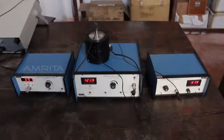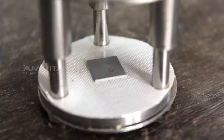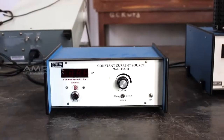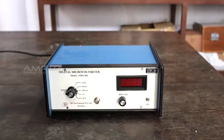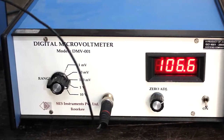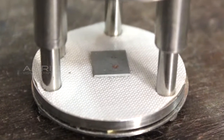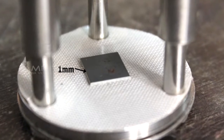Apparatus: the experimental setup consists of probe arrangement, sample, oven measuring 0 to 200 degrees Celsius, constant current generator, oven power supply, and digital panel meter measuring voltage and current. This method is employed when the sample is in the form of a thin wafer, such as a thin semiconducting material deposited on a substrate.